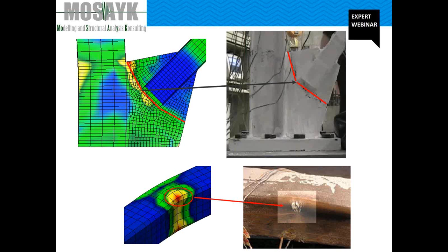Here, the ability of the Midas FEA model to reproduce the experimental behavior is clear. An appropriate detailing of the clearance at the gusset plate is fundamental for the brace to accommodate buckling in the out-of-plane direction by forming a plastic hinge at the gusset plates rather than at the brace end. That's a key point in the performance-based seismic design of structures, usually called hierarchy of resistance.